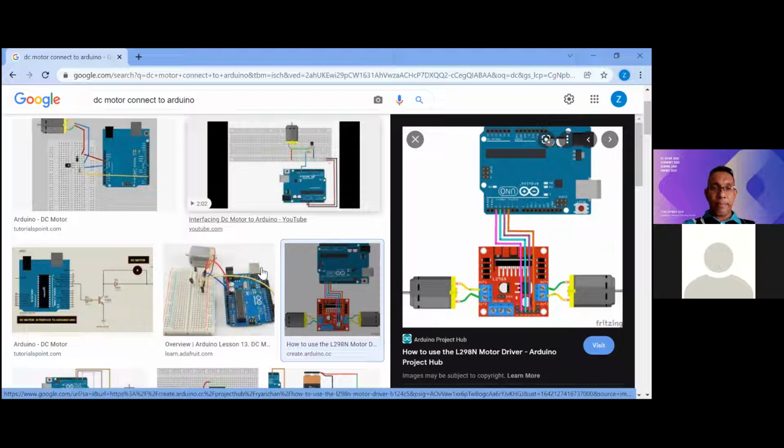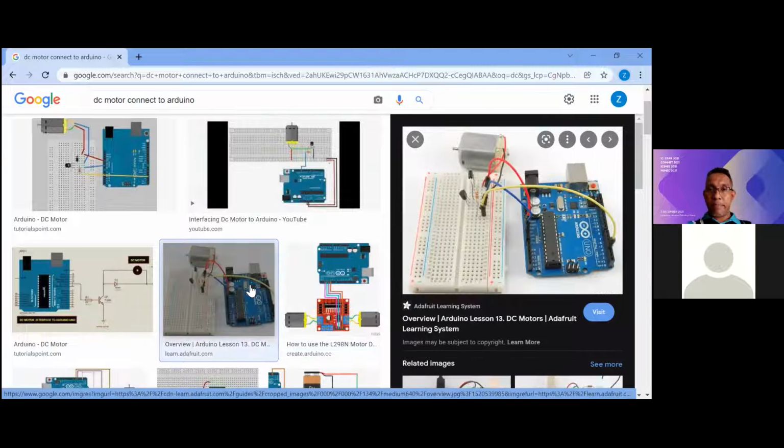In this case, can we control the turning of the motor anti-clockwise? Yeah, of course. The direction also you can control, because they have 0 to 5 volt or 0 to -5 volt. If you change the direction, they go to the reverse current. So the -1 is to change the direction. On the motor you can see the black and red here. So there is also a purpose for clockwise and anti-clockwise direction. Okay. All DC motors can do that, can reverse the direction. Oh, okay.